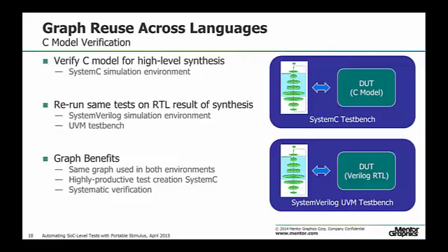Typically, this would be verified in a System C simulation environment. So we could create a graph that drives our System C environment. Then, after synthesis, where we have generated the RTL model, the same graph could drive a System Verilog environment or a UVM test bench, but it would be the same high-level graph that would be reused to do systematic verification in both environments.